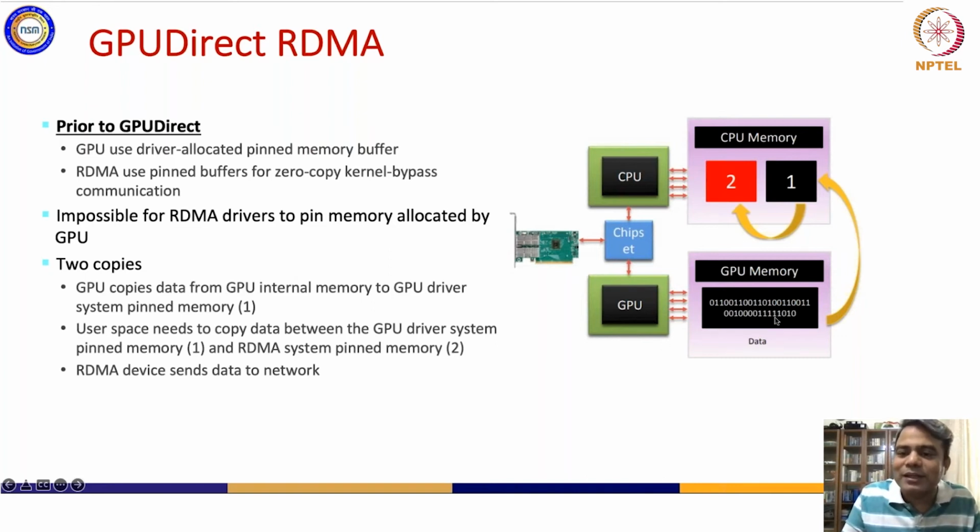When you are trying to accelerate a workload onto a GPU, you will copy the operands from the CPU memory onto the GPU memory. The GPU will then do some matrix vector multiplication, matrix multiplication. After certain iterations, if it needs newer operands, it will write the result onto the CPU memory and get some new operands. All this communication is done from the CPU and the RAM through the chipset to the GPU memory.